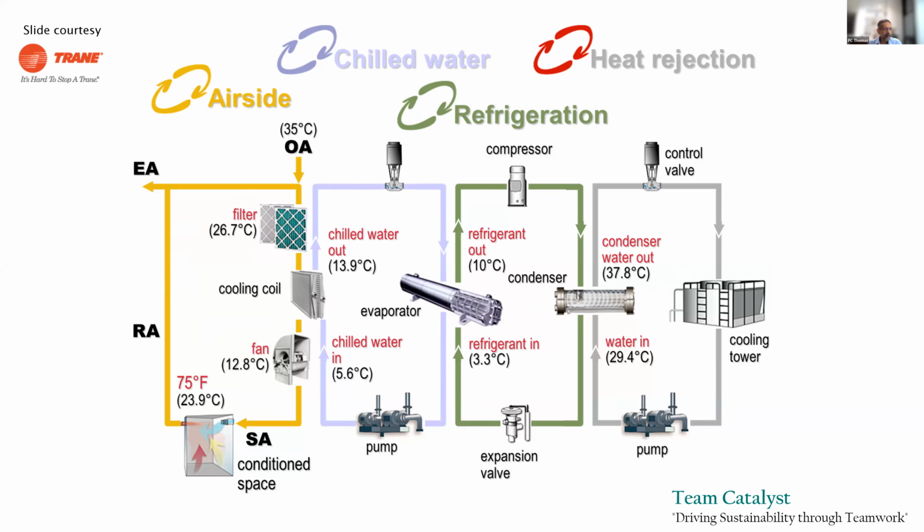Now, in a VRF type machine, it too has a compressor, and that compressor also gets warm when it is doing work. In the chiller, when the condenser gets warm, we pump water from a cooling tower into the condenser side of the chiller and cool it down.